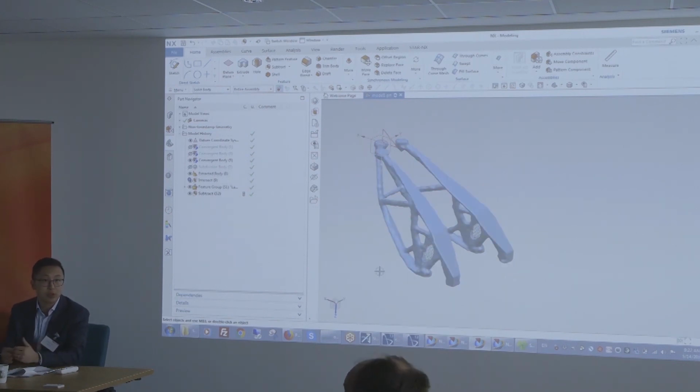So the lattice gets smaller and smaller, and effectively you're calculating equivalent solid properties. It'll just look like a solid, but it won't be as stiff as a solid. And it might have orthotropic properties depending on which way the lattice is facing.